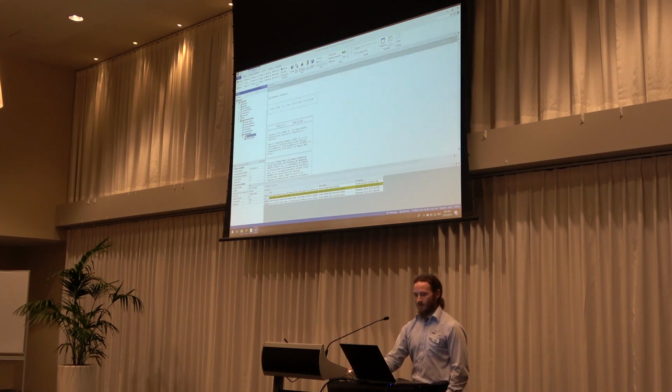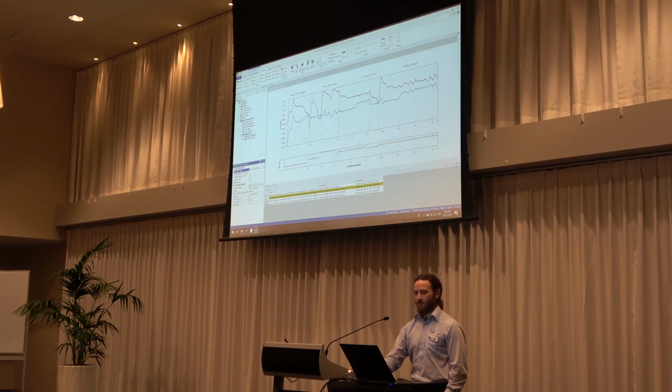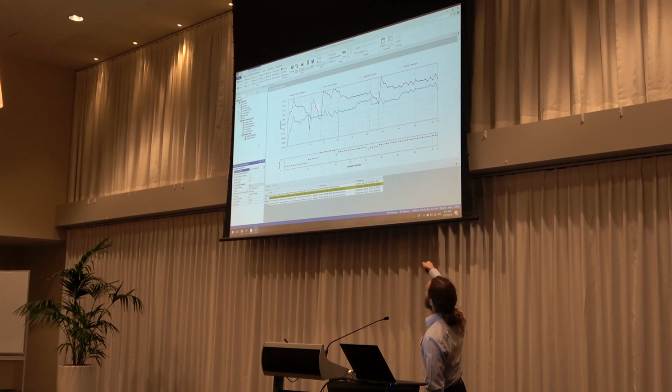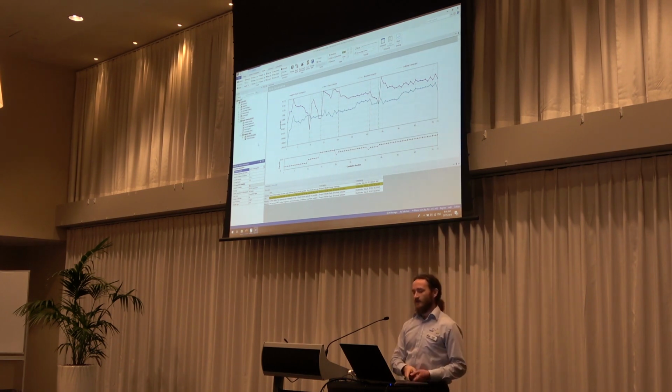And if we look at solution information, sorry, first I'll show you the force convergence. Okay, so this is your typical force convergence plot. It's going along nicely, lots of green lines, which we like seeing, and then suddenly it fails to converge. So at this point here, it's switched to the explicit solver. Now, because it's not a GUI feature yet, we don't see anything happen there.